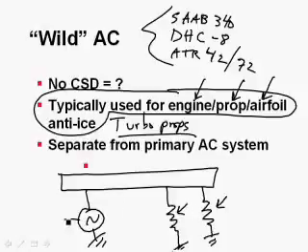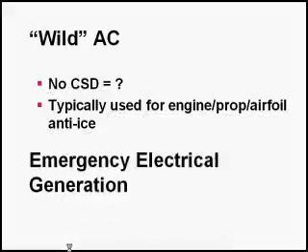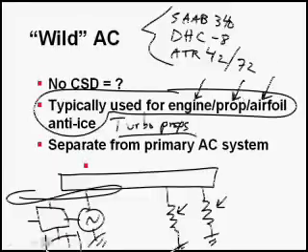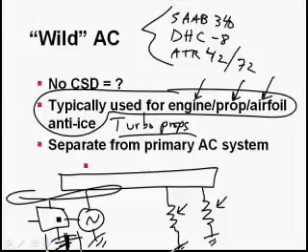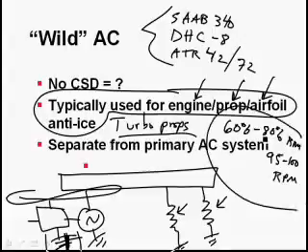The nice thing is, this is being driven off of the propeller reduction gearbox, so we've got a propeller, and it's being driven by the engine, which I'm not going to draw in. It's being run off of this propeller, and if you know anything about turboprops, typically they idle at around 60 to 80%, and they typically run between 95 and 100% RPM. Now, these are RPMs. These are not power settings.